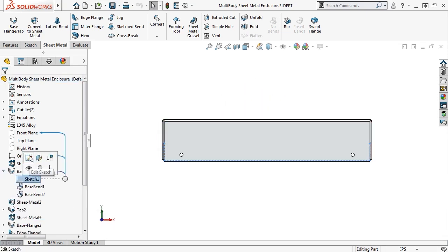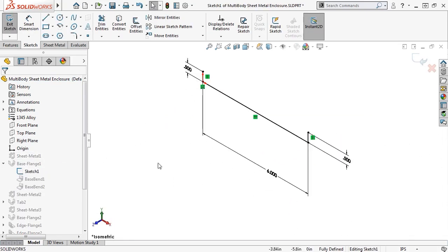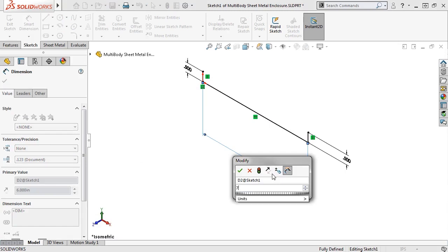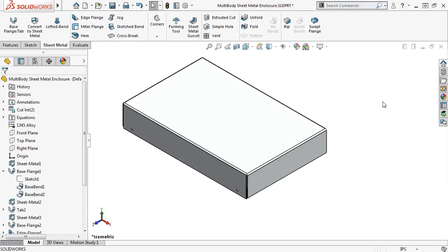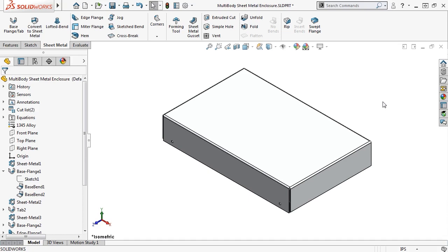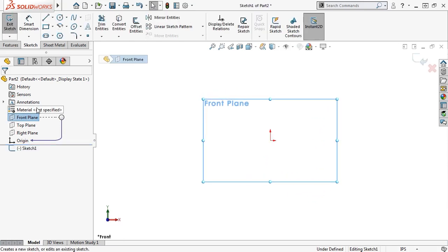If you're comfortable using top-down assembly design, then you know how powerful it can be having in-context features that drive the geometry for both pieces of sheet metal. With multi-body sheet metal design, the same power is extended to the part level without the need for any complex in-context file relationships. In this example, I want to create a simple top and bottom cover for an enclosure. I'll create both bodies here in the same SOLIDWORKS part file. I'll get started with a basic sketch for the bottom cover.